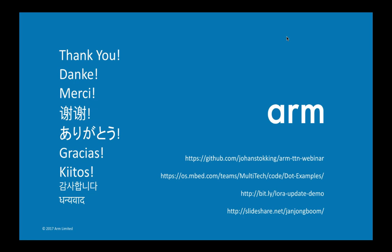Yes, in LoRaWAN 1.1 this is indeed redefined to be the join EUI, and typically the so-called join server will issue the join EUI for you. Depending on which party you trust with your LoRaWAN root keys, you get a join EUI, and this is a reference for the network server to contact the join server of choice.